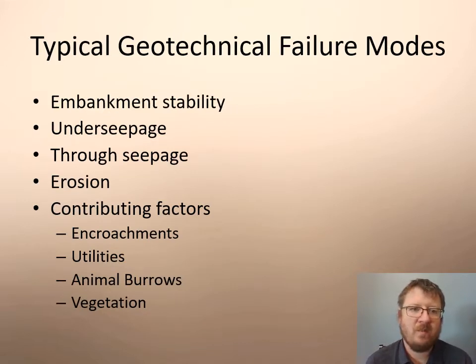So typically for levees and embankments, dams and levees, there are several common failure modes, including embankment instability, underseepage, through seepage, and wind or current induced erosion. And these failure modes can be exacerbated by other factors such as encroachments, utilities, animal burrows, and poor vegetation on the levees. So those can contribute to the likelihood of failure or the resiliency of a structure.